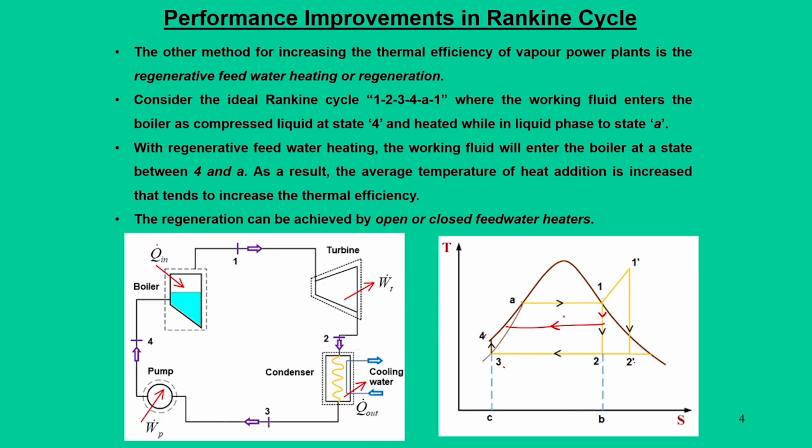Suppose during the expansion from 1 to 2, 1 unit of fluid is entering, and you tap y amount of fluid or steam through another process. That is what we call a feed water heating system, and the rest we expand in the turbine.